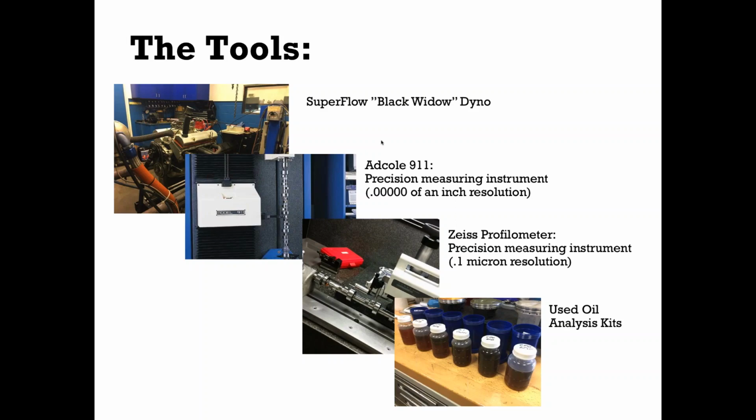All of us that have ever run a manual dyno know that the driver has an impact on the dyno. This one is completely automated, with both servo valves. It's got 2 servos on it, both an inlet and an outlet under automated control, as well as the throttle. For a water brake, it's got exceptionally good repeatability, which is key for our testing.